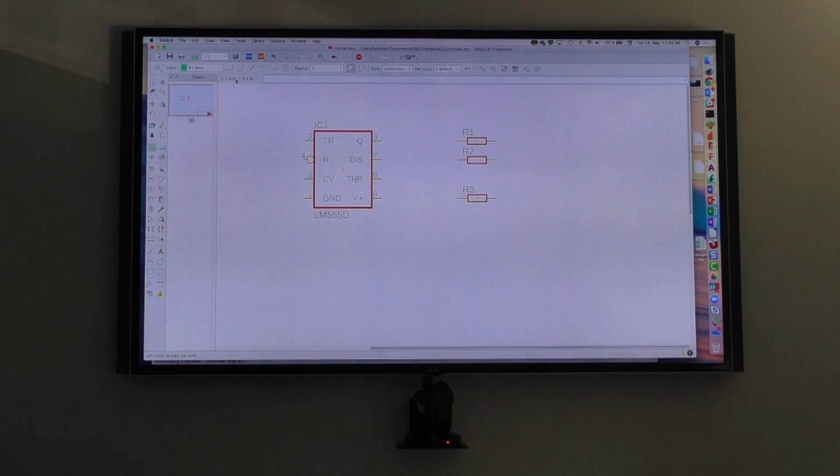Some minutes before I joked about the inches. Here we have them. That's the reason. The reason is that when we started with Eagle version 1, all the components were produced in inch-based grids. Everyone will do it. And no, that's not correct. Siemens were the first who started to make components in millimeters. But Eagle also calculated in mils in the beginning, and so that's the reason why we have this 2.54 millimeter.